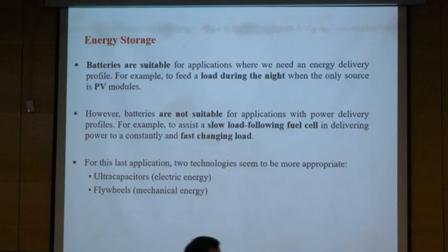When we charge this package, we charge the lithium ion, and then we convert the DC voltage, so we have one conversion here. Assuming the DC-DC converter has 95%, 93, sometimes 98 percent efficiency, we have, for example, 5% losses here.